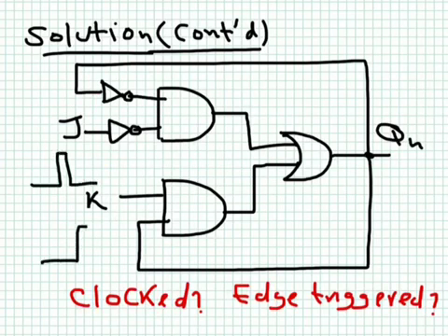And you will see later, when we talk about delays, how to create a delay in order to use it to create such very short pulses at the input. And these short pulses will allow you to set, reset, or toggle, but they have to be very short, a very short deviation from the do-not-change state.